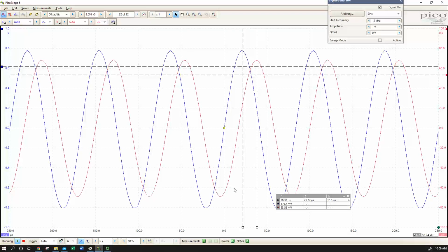So we can look at frequency on the x-axis as opposed to time. And resonance is a great time to do that, because everything with a resonance circuit is frequency dependent. We know that things change dramatically with very small changes in frequency as we get around resonance, more so the higher the Q factor of the circuit.